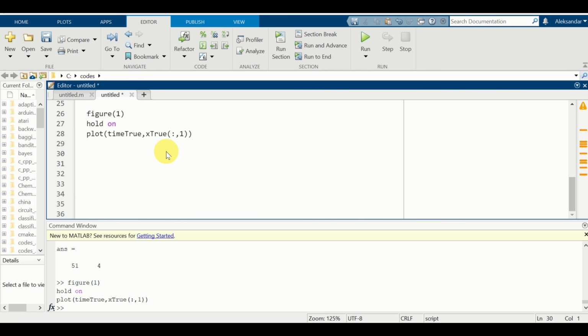Okay, so I will create a vector pole location, and I will select the following poles. The first pole will be at -4 on the real axis, the second pole will be at -6, and then I will have 2 conjugate complex poles. One will be at -2 plus 2i, where i is the imaginary unit, and another one will be a conjugate of this pole. It will be at -2 minus 2i.